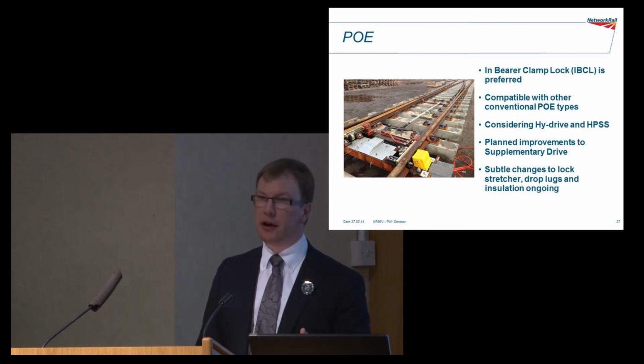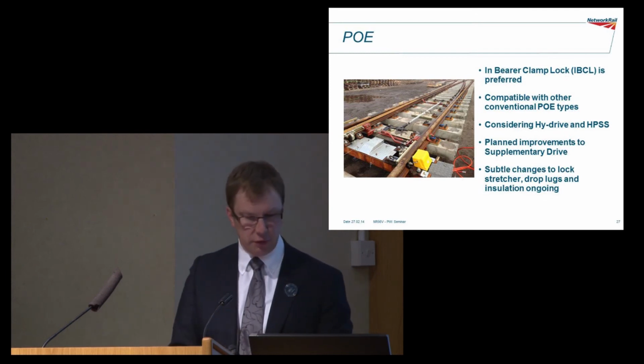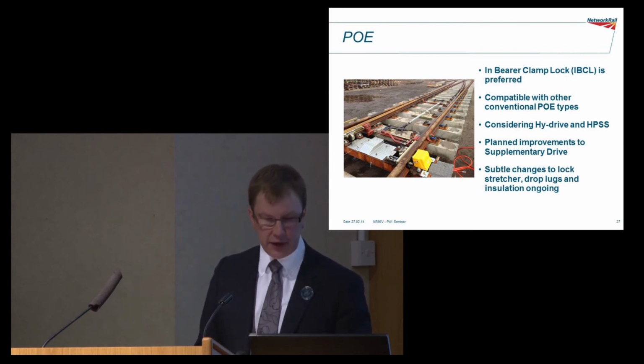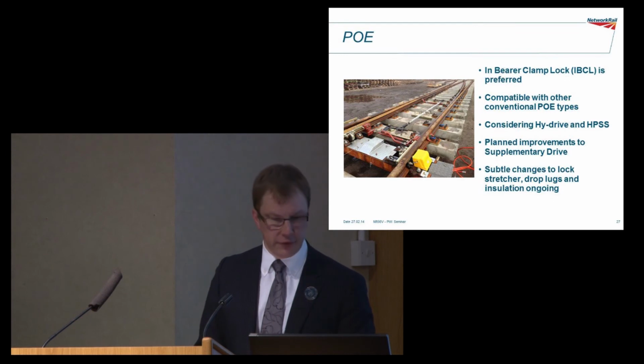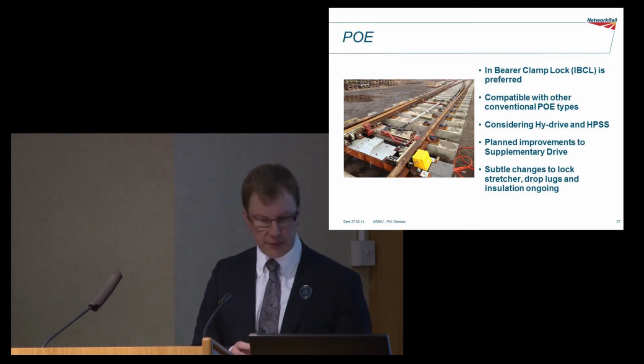And we're also working on subtle changes to the lock stretcher bar, basically enabling us to put a bit more metal in it to try and resist the fatigue failures we get occasionally in those. And to the drop lugs at the front for the detectors when you've got a point machine, this is to enable the points heating to be extended towards the tip.